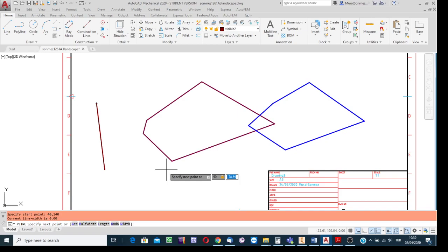If the line is to extend to the right, then delta x is positive. You see the line is ready to extend to the right, delta x positive. If the line is to be created to the left, then write delta x as negative. Since I wrote the number as positive, now you see AutoCAD simulating the line as extended to the right. But say the delta y value is not input yet. Shall you create the line upwardly inclined or downwardly?